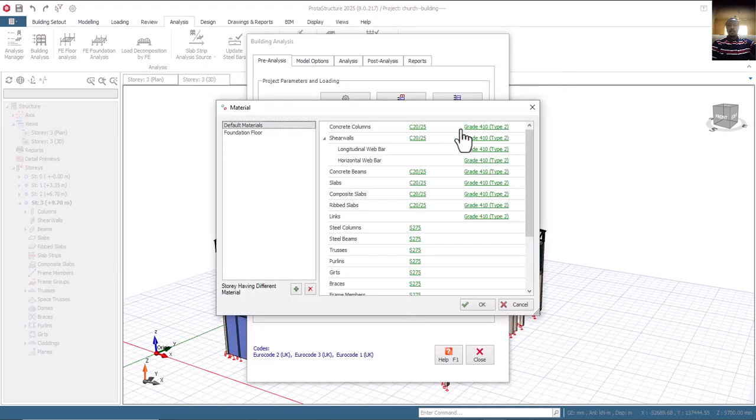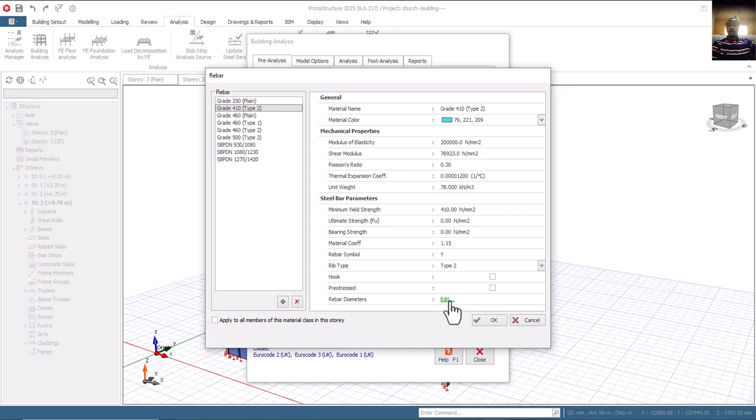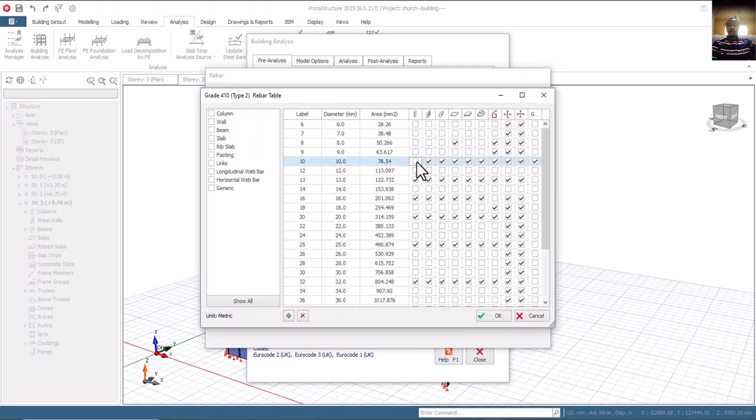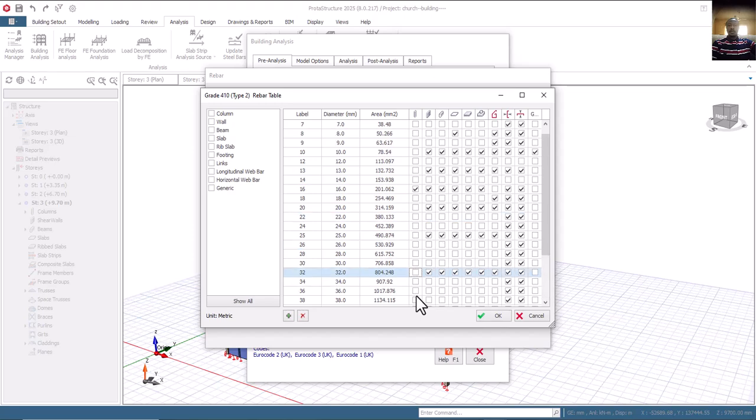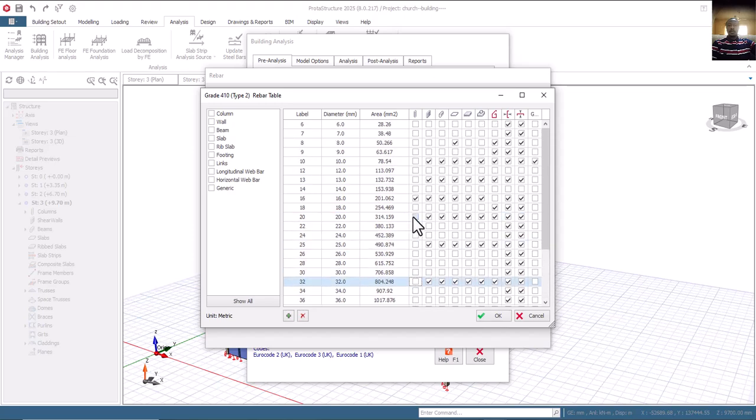So I'll go back again to this, then click on any of these, then I have to change this. Okay, for my column I'm using a 16. Is that okay? I don't need 20. 16 should be okay. Okay, let me put 20. Yes, for some places let me put 20. Then I have a wall, so this wall I want to use a 12 and 16. Every other thing remove. We can even use 20 also, but that we are choosing 20 does not mean we are going to be using 20. Is that okay? We want to work out within the range.